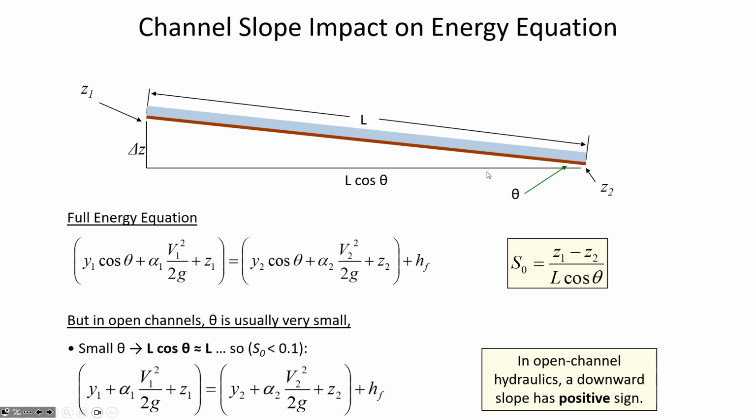One thing, though, that takes a little bit of getting used to is that when we were dealing with pipe flow, it was possible that water could be flowing up a hill. If it's enclosed in a pipe, then water can flow uphill. Although the pressure will be decreasing, it could be that the uphill section is just temporary and all of the other surrounding sections of the pipe are downhill, so there could be a temporary inverted siphon effect. It could be that there's a pump.